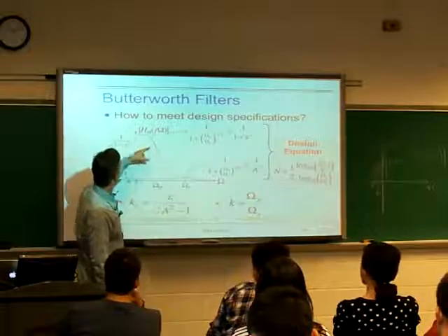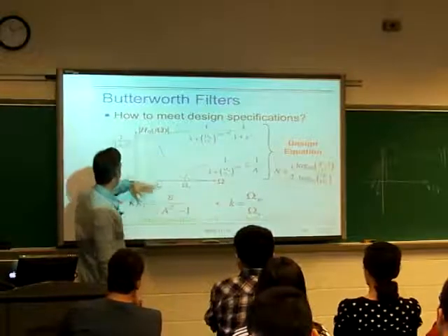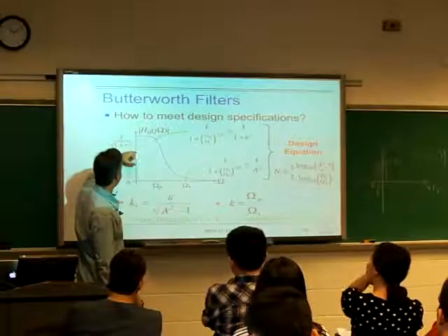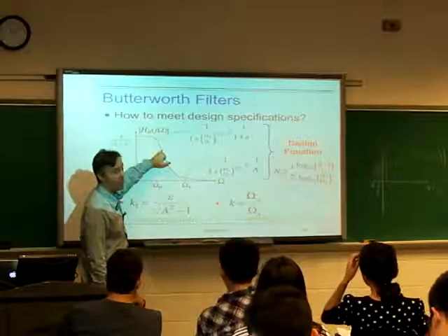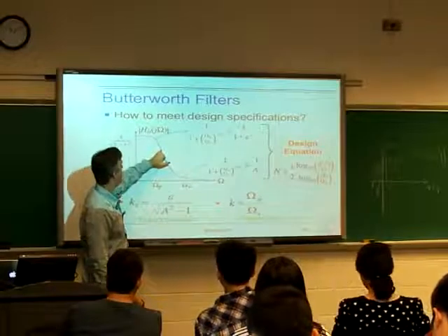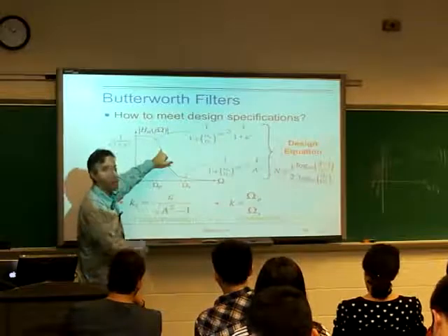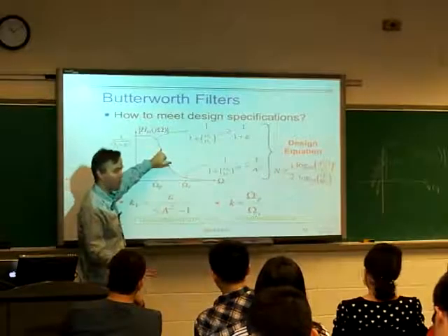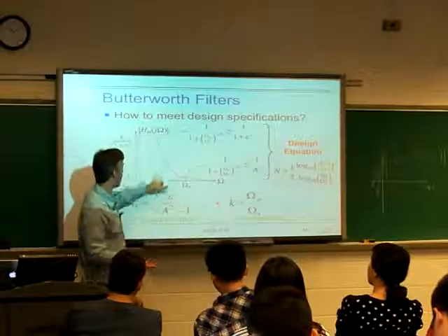So here, this is linear frequency. This is magnitude of H(jω). So omega c is the 0.707 point, the 1 over root 2, which will be here. 3 dB, exactly, yeah. So the point is that, when we characterize these filters very broadly, we use the 3 dB point as a way of characterizing a filter family. But this is about the actual specification of my application.